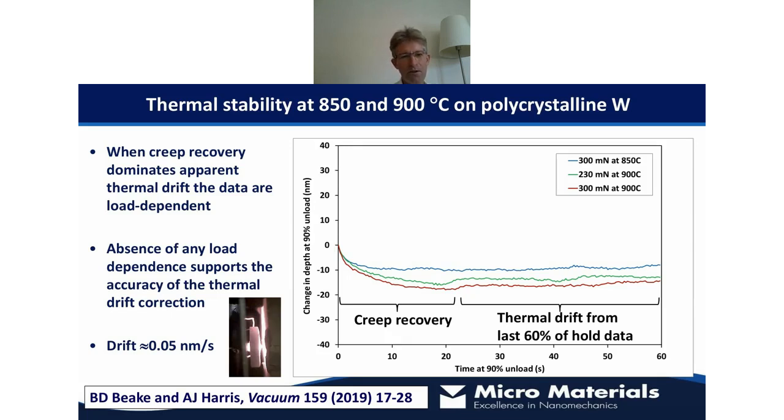is that when you have a lot of creep recovery, which you might see on a polymer at room temperature, for example, viscoelastic recovery, then you'll get a lot stronger initial decrease in depth at higher load, because it's a material response. So the idea is that this creep recovery process creeps out after the first 20 seconds or so, and then you can use the last 40 seconds of the data for an accurate thermal drift correction.